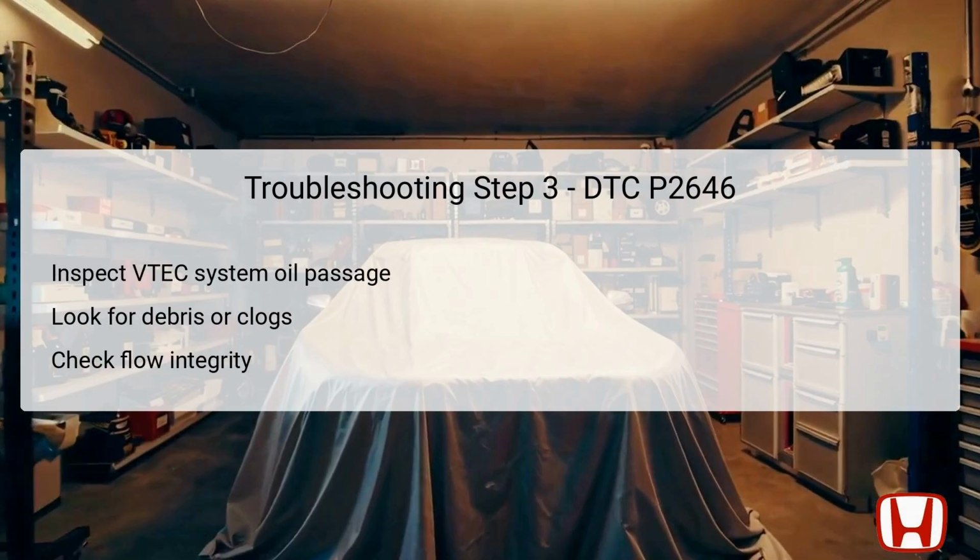This step involves inspecting the VTEC system oil passage for any obstructions that could impede oil flow. Debris or clogs can prevent oil from reaching vital components, leading to decreased pressure and therefore triggering DTC P2646. You should carefully visually examine the passage for any visible foreign materials.